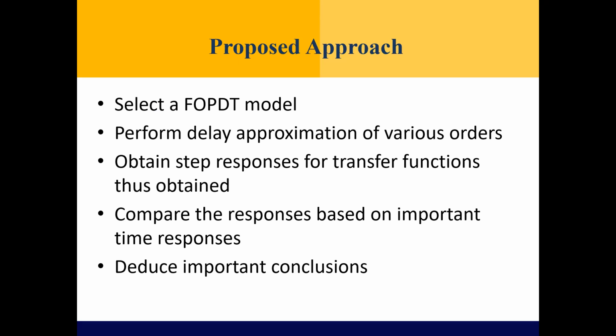So this is the proposed approach, where we have selected an actual model from the paper industry, corresponding to the headbox consistency. Here we have performed the delay approximation with various orders: first, second, fifth, 15th, and 20th. Then we have obtained the step responses for the transfer functions for all the orders, compared all the responses, and deduced important conclusions from there.